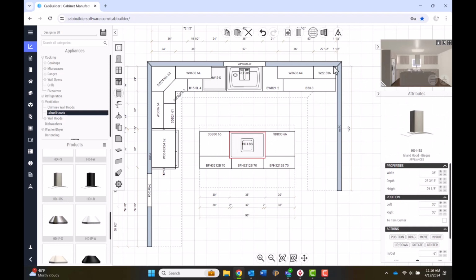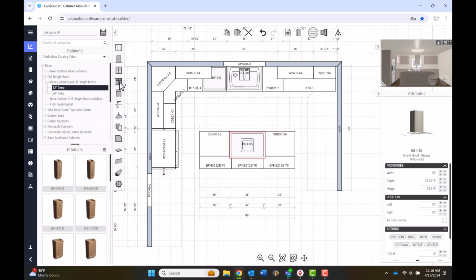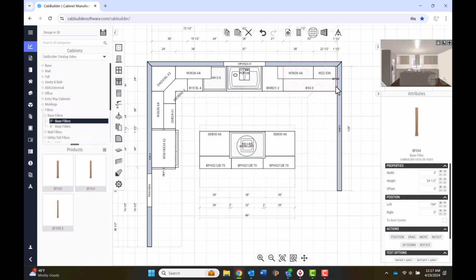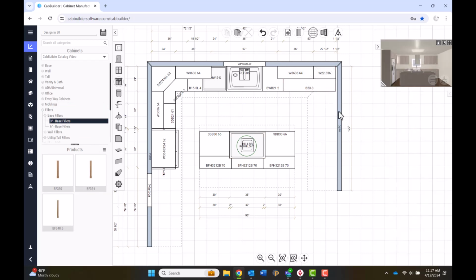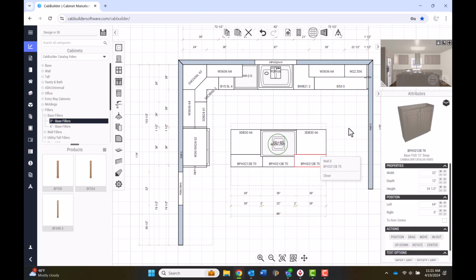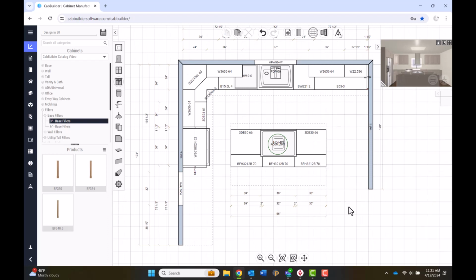If there is a need for fillers between cabinets and an adjacent wall, if the adjacent wall zone is on, this may cause a disruption in the attempt to place the filler material. To make this task easier, you may turn the adjacent wall's placement zone off. Click on the adjacent wall to launch its Attributes box. In the wall's Attributes box, toggle off the front wall zone by removing the mark from the box to the right. Now, when we drag and drop the filler into that small gap, it will place easily in the appropriate orientation and will auto-cut to fit.